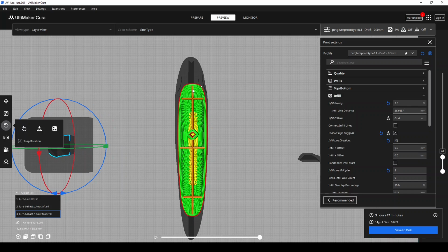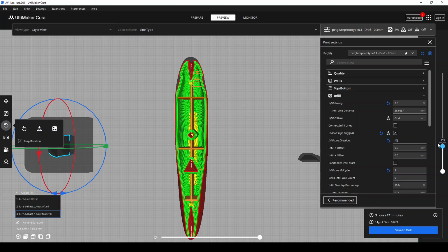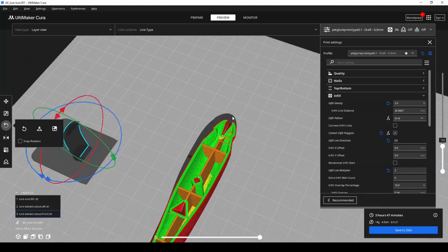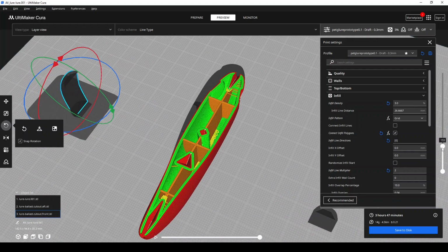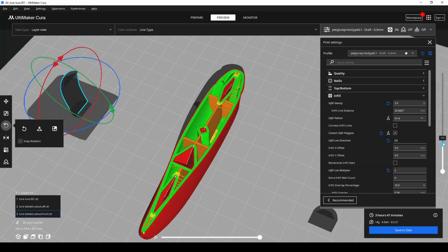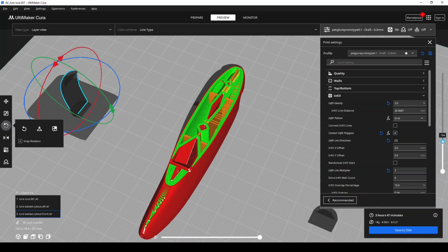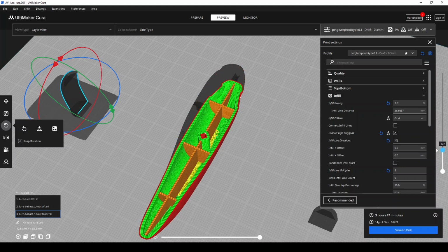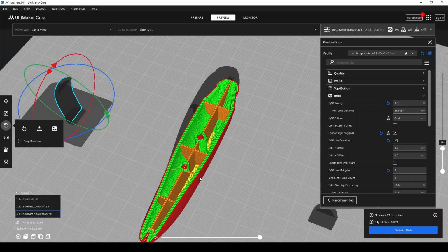The big thing to me is that I've got this line in the middle, and as it goes up, since we printed everything with 45-degree angles, it all starts on that. And it's a support for it, basically. So all of my line ties and my ballast pockets at their low point are resting on that, and it gives it a place to start. And that's why we like the 45-degree angles, because as you go up, you don't need that support on the outside.